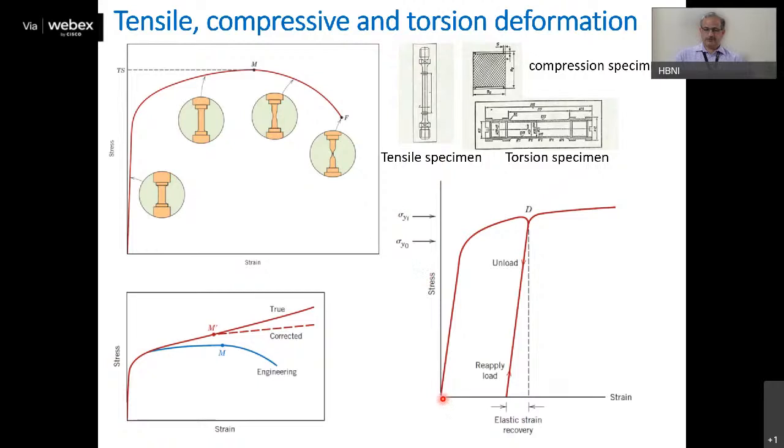So basically, when you apply stress, it undergoes plastic deformation certainly, but there is no such kind of behavior. So it goes on increasing, and in between, actually, there is some strengthening also happening under the plastic deformation, because the microstructure evolves, as we will discuss in a later part of this talk.